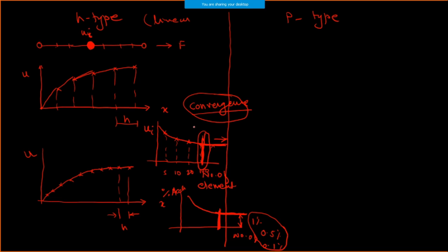But as we increase to a bigger and bigger size, what is going to happen? It is going to take too much time for a computer to do that many calculations. That is what is called computational effort. But from this point onward, if I increase my computational effort, it will not affect my accuracy, and that is the limitation. That is the point called convergence.